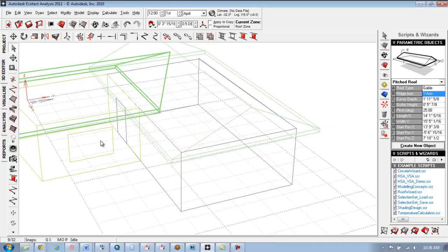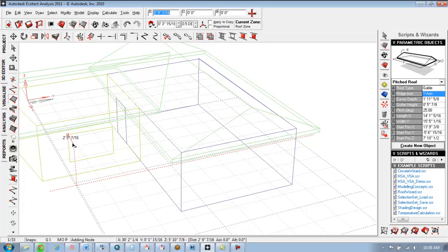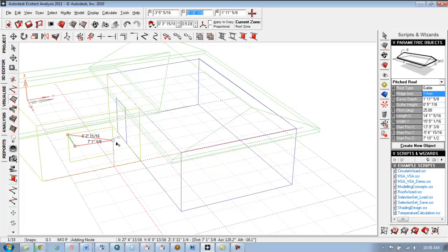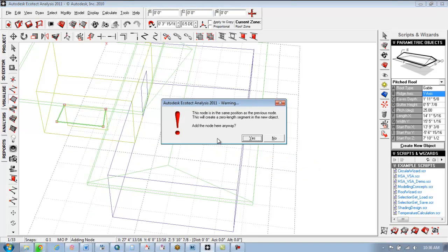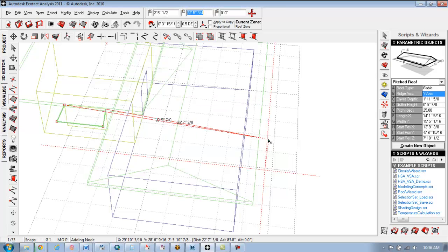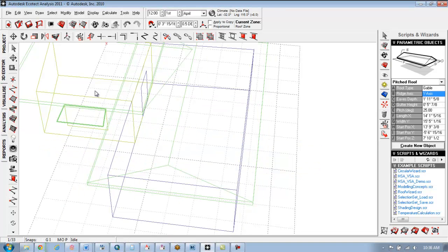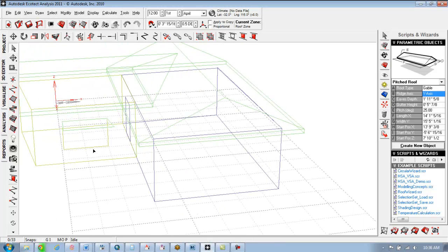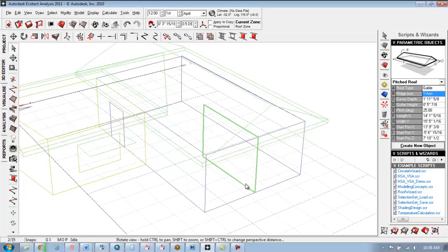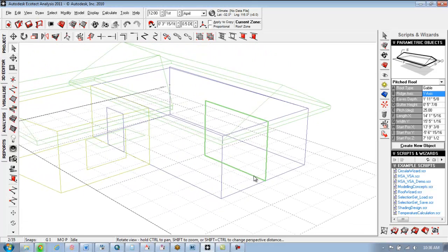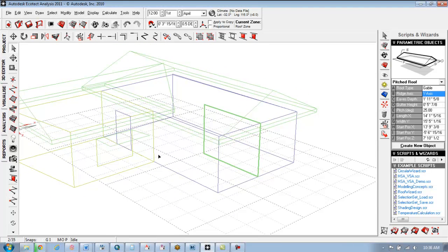You can also, there are other objects here. You can create partitions, you can create planar surfaces. So if we had a shading device, plug that in there. I always forget to hit escape on that last one. All right, or if you had a room partition on the interior, you can plug that in. All right, so then you have your nicely modeled building.